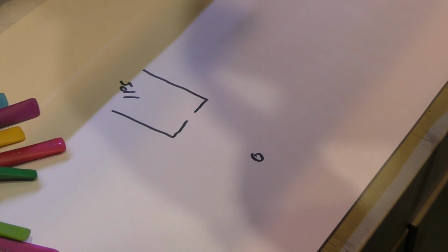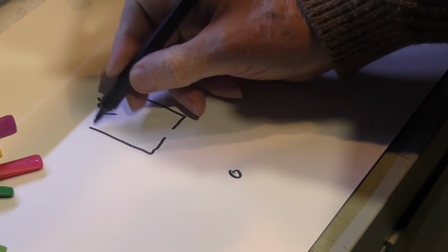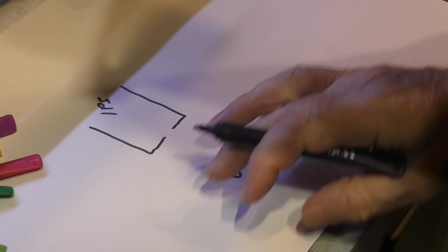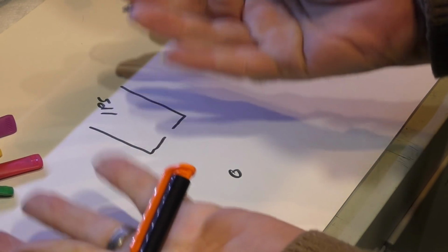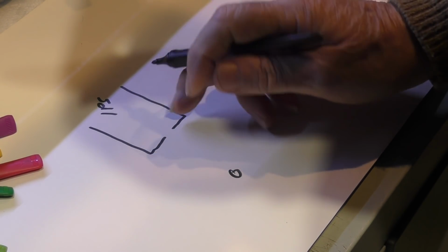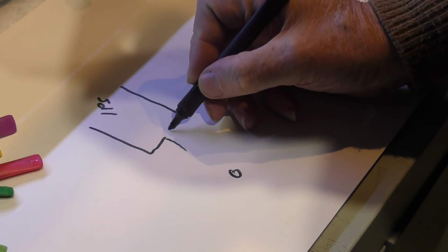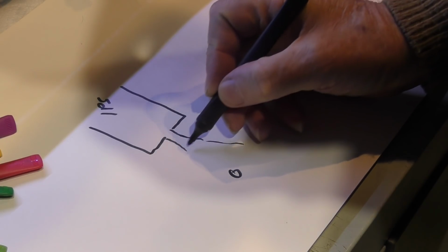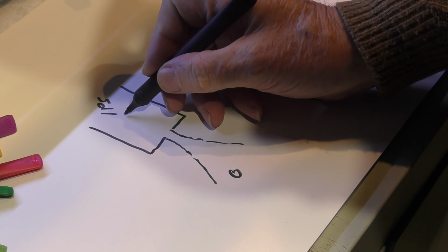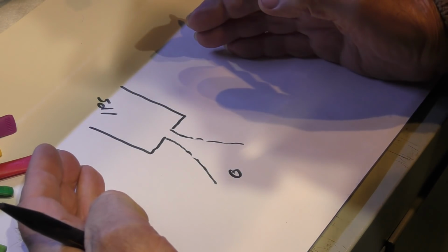Right, we're now into one of my dodgy diagrams. Look, I've got a nozzle here, an orifice, which has got 1 psi inside the system coming from a pump, and I've got 0 psi on the outside because that's what is just here, nothing, atmospheric pressure. So what will happen is the air will build up through this nozzle, and it won't flow very evenly because this is a sharp-edged orifice, but it will come out of here and it will probably take a shape something like this, and then it will gradually do this because at 1 psi there isn't a huge tendency for that air to want to expand outwards.